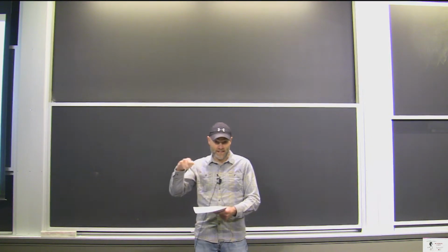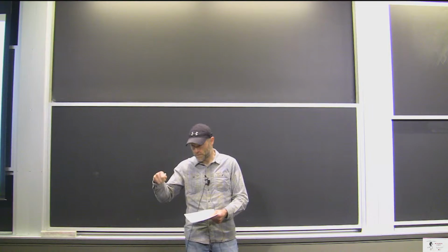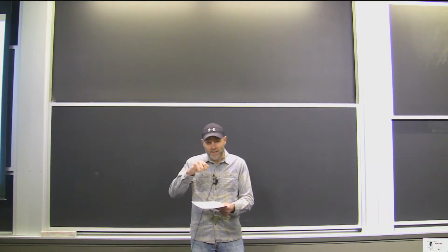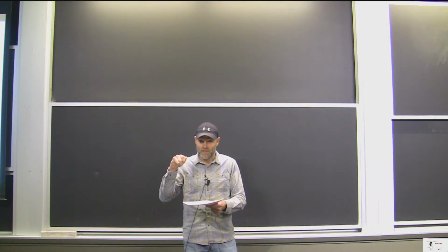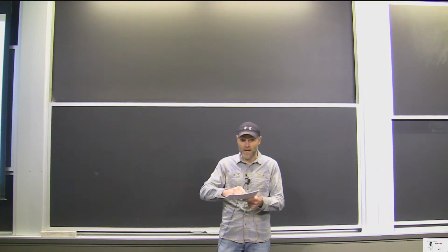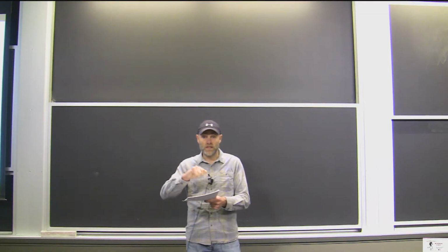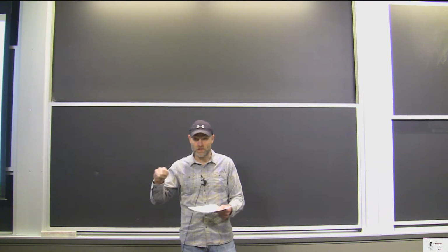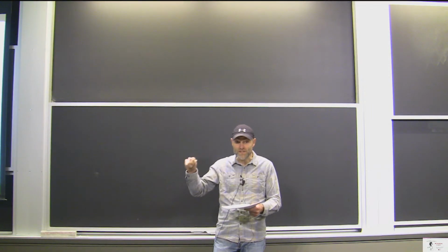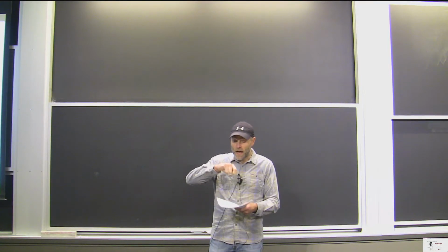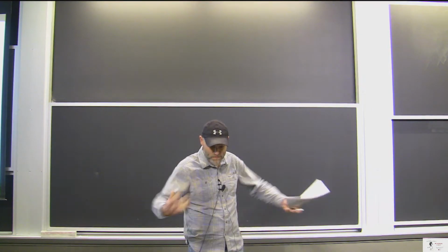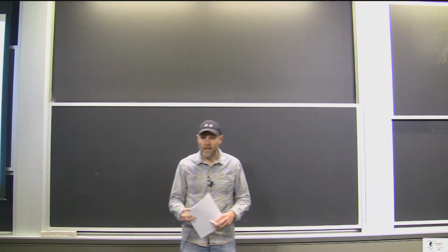And in the last lecture, we got many more degrees of freedom with our humanoid. The big point last time was actually that if you have enough degrees of freedom, some of the dynamics problems actually get easier. And I hope that point landed, that you can start abstracting your dynamics into thinking about the dynamics of your center of mass and your angular momentum, which are maybe easier than thinking about all your joint dynamics.